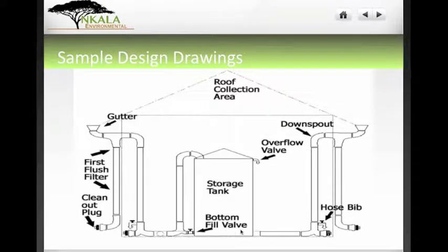And so it can fill either from the bottom or from the top, depending on how we want it to do. And you see you have a spigot here, you have another spigot here. So this is for withdrawing water from the tank. And you also have this bottom valve, so we can keep it open during normal operation. If we need to close it, if we need to empty the tank, it's there. So you see all of these, and you see the overflow valve, which of course is very important. So if the tank is full, it doesn't back up into your gutters and start causing problems there. It just overflows. So this is a very important aspect of your design, is having drawings to represent the things that you plan to do.